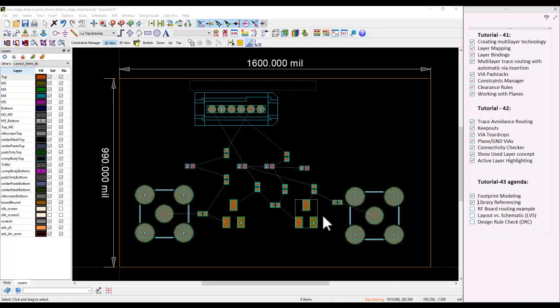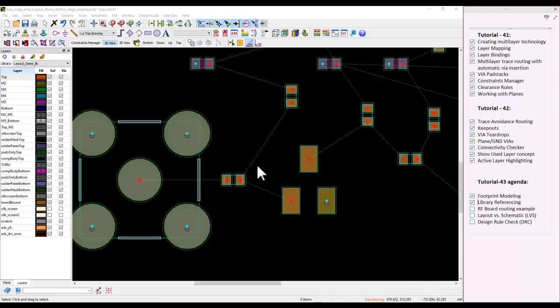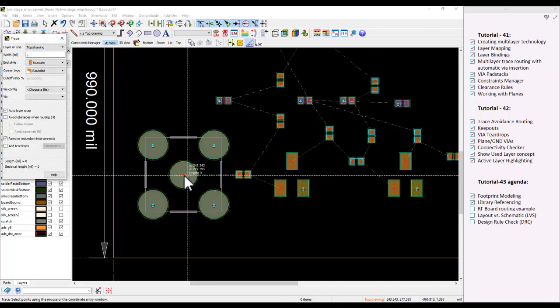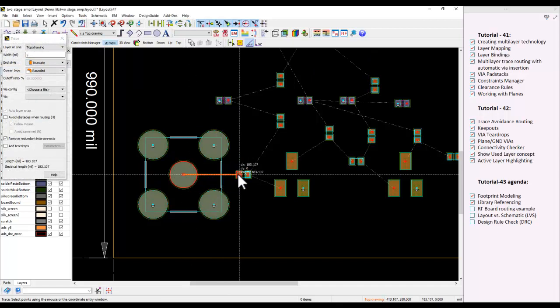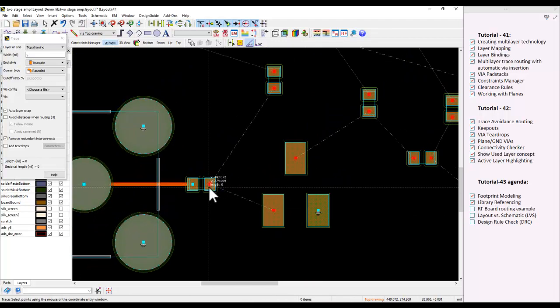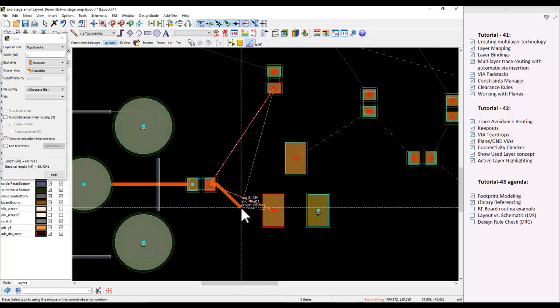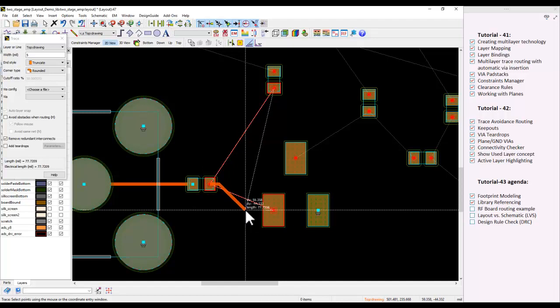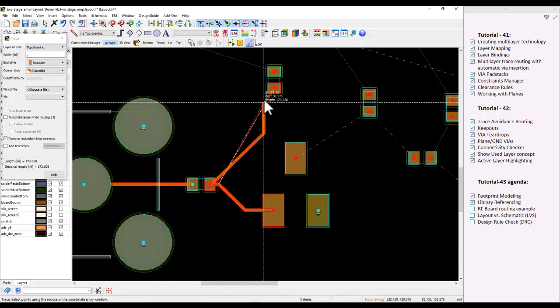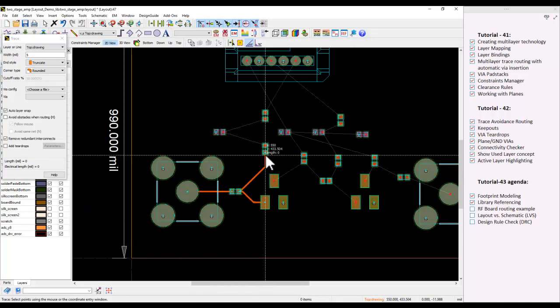I just placed the components in a logical order. And now you can also see the rubber band between those components. And now using all the knowledge, I'm sure you will be very comfortable routing this. So here in this case, we can decide top, which is basically the top layer here, because I'm using my colleague's example. And now using these connectivity modes or the guiding lines, it's very easy for us to go ahead and start routing the board as we require.